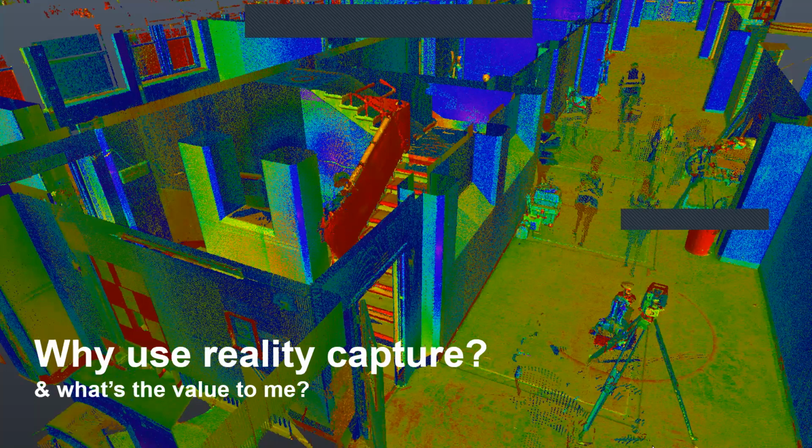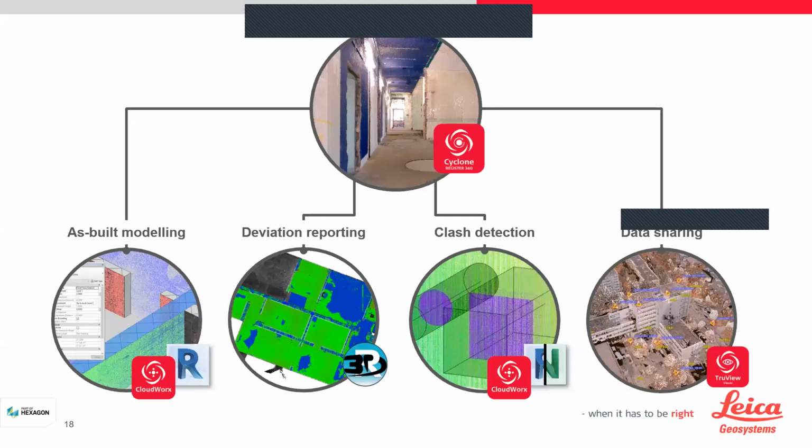We can use it for analyzing what is there on the site, how to change it, and what the dimensions are. We can use it for as built modeling when we want to model objects from an actual site in reality, which might be an old construction site, or a construction site you are currently working on, or it might be a heritage site where we want as built models. We can do deviation reporting based on floor flatness and tunnel analysis. We can have volumetric analysis for cones and cylinders. We can have analysis for fuel storage tanks.